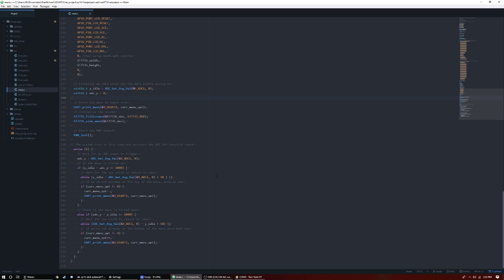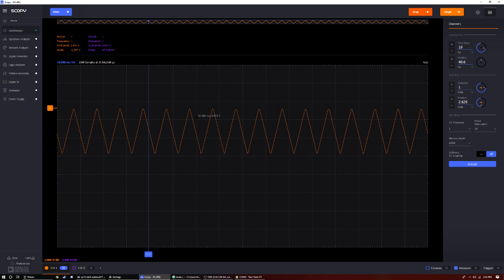I suspect if we had a faster clock for the timer, we could achieve better rates and make tuning the frequency possible. But it doesn't really make sense to have that type of resolution when changing the prescaler by even a value of 1 causes such a drastic change.